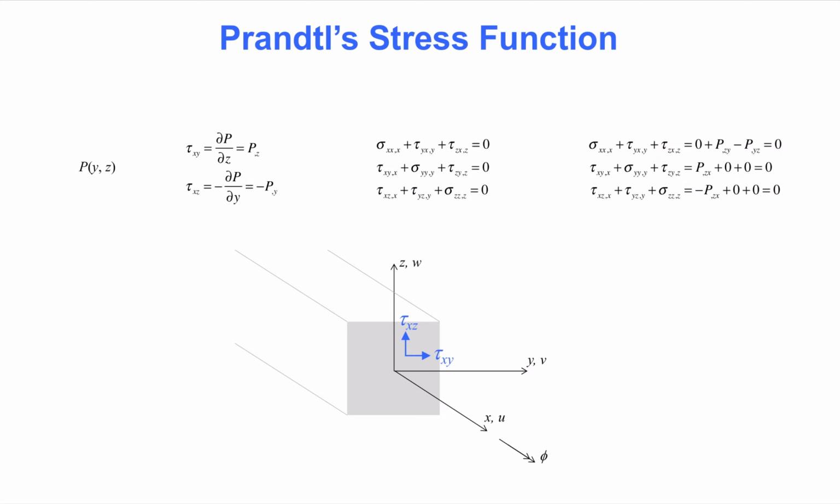stress. The prominent use of stress functions in general St. Venant torsion should make us question why the theory is named after St. Venant. That is because St. Venant formulated the theory in terms of an unknown function that represents the axial displacement at any point of the cross-section. It was Ludwig Prandtl who reformulated the problem in terms of a stress function, which is the way we address torque carried by shear stress today.